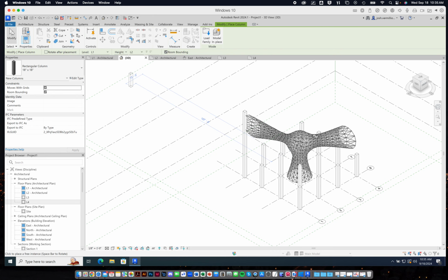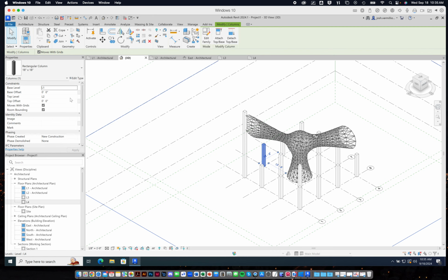Oh, nope, okay. Apparently I have to set all of these now to their tops to be level 4, right? So what I'm doing is I'm selecting these objects. I can see their properties here, right? Now instead of having something over here in Grasshopper and something out here in Rhino that I'm looking at, it's all in one interface. But now I can start to say, what's the top level? I can give it a specific height, or I could say, whatever level 4 is, if I move it around, these things are going to update with it, right? So again, we're building in associations with these things. Is this making sense so far?